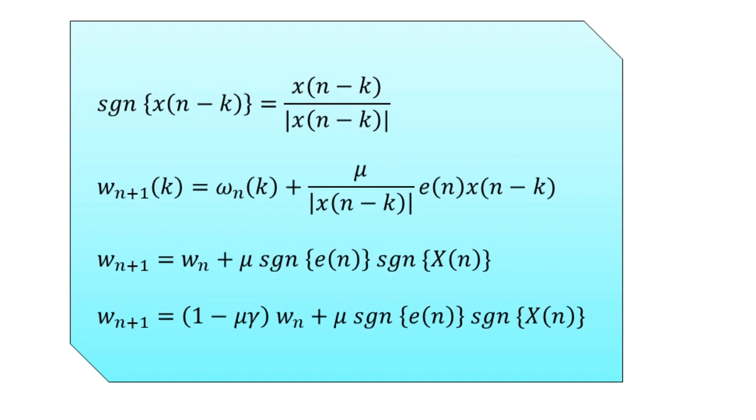Now we are going to have a brief discussion with respect to the third and the last type to be discussed, that is the variable step size algorithms. As we have seen in the mathematical expressions describing the LMS algorithm, there is the use of a step size denoted by mu for selecting the step size in the LMS algorithms.